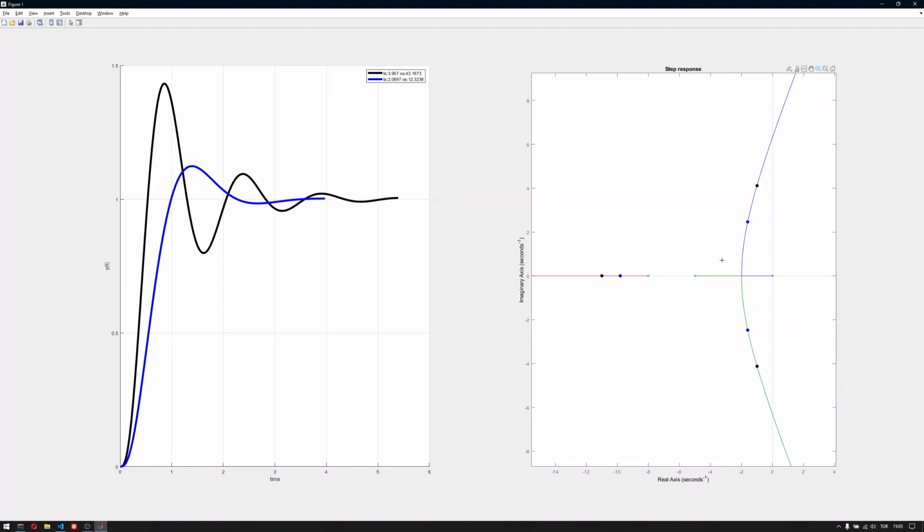So if it's closer, the settling time value will be less reliable, because it is just modeling the settling time of this pole pair. They should be alone, but they're not. A third pole approaches them, so therefore the settling time formula is not really correct, because we have a third order system, not a second order system. The same goes for actually the black ones here, but since it is 10 times further away, we have a better result. It is almost 4 seconds, so not that big of a deal. 3.95 is quite close to 4, so it works if it's 10 times away.